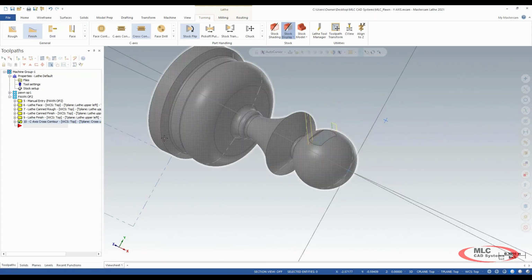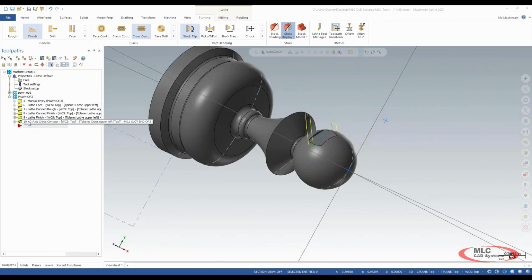Now, one thing that I talk about is how easy it is to get the toolpath. Another thing I want to discuss, I showed you how to move an operation around, but there was another option here as well, copy before and copy after. I can also copy operations and edit parameters.